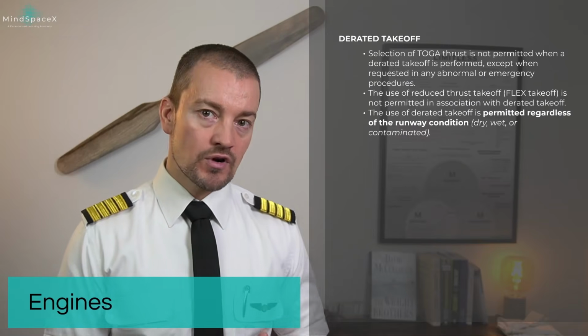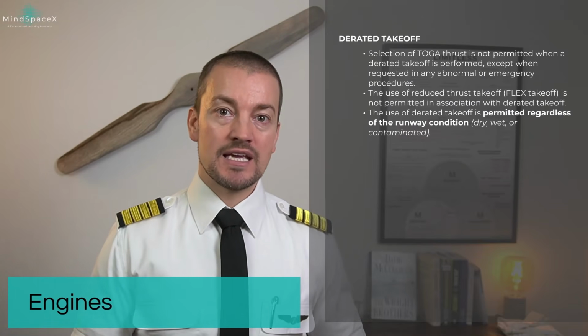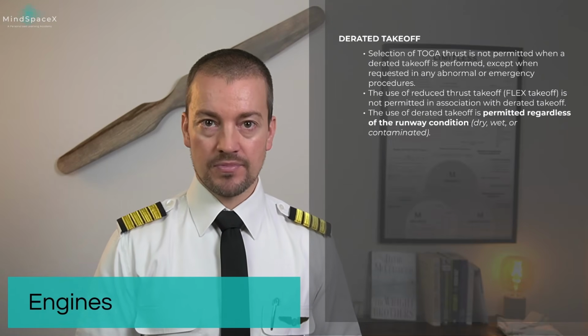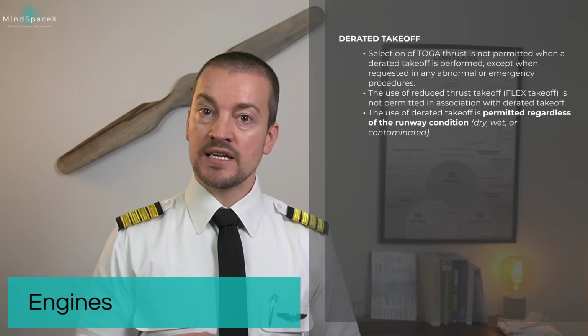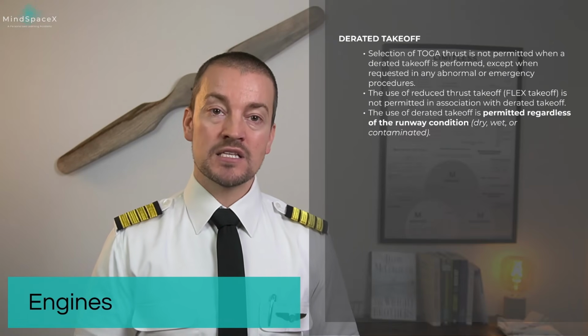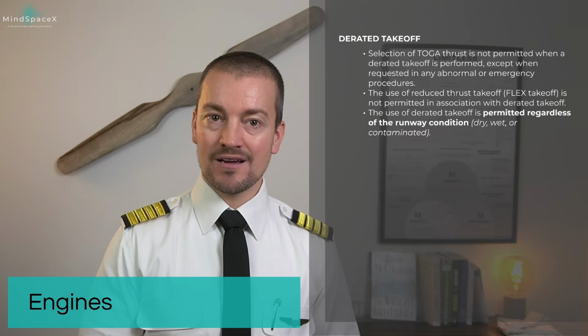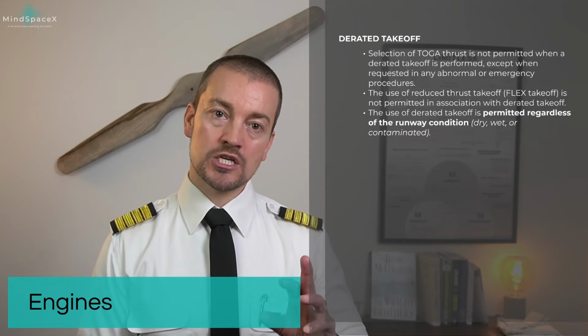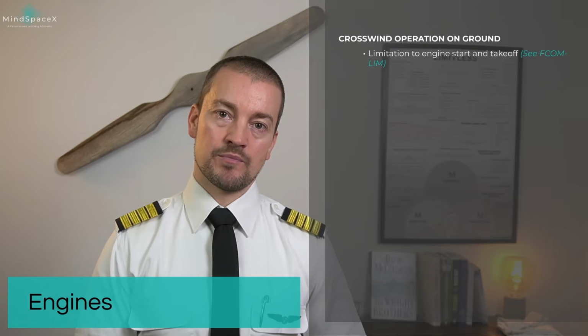The use of reduced thrust takeoff, flex takeoff, is not permitted in association with a derated takeoff. And the use of derated takeoff is permitted regardless of the runway conditions. That means we can use a derated takeoff for contaminated runways, something that's not possible with a flexible temperature.